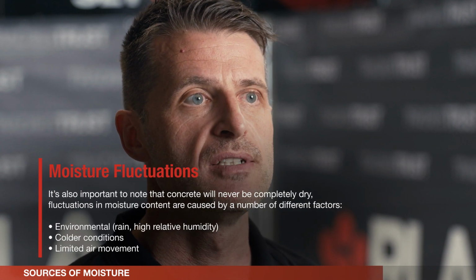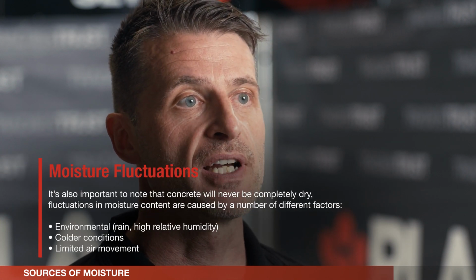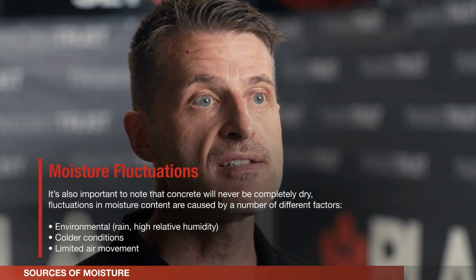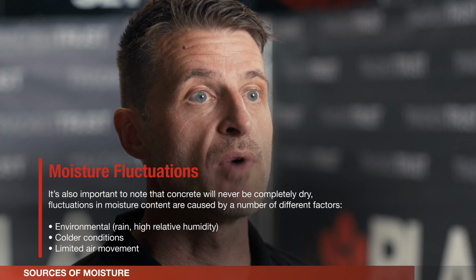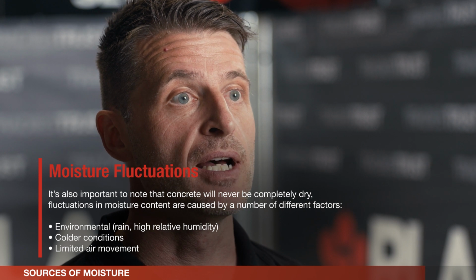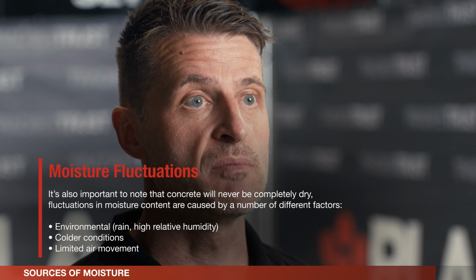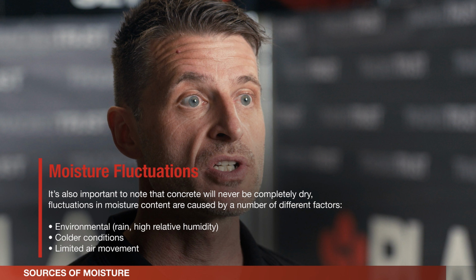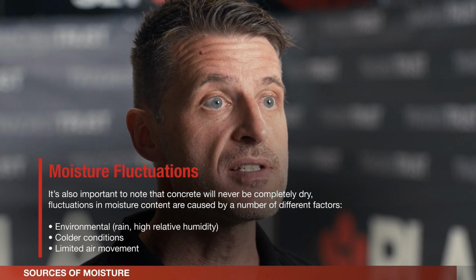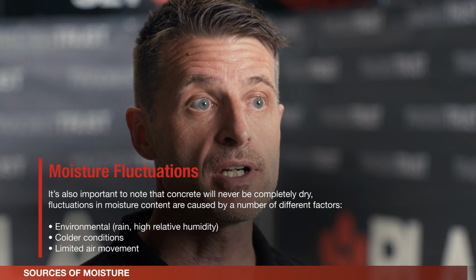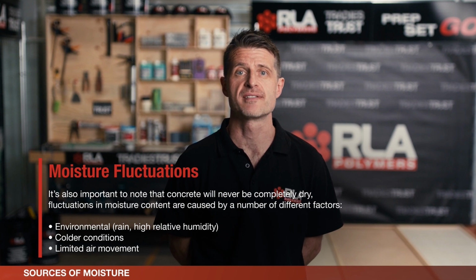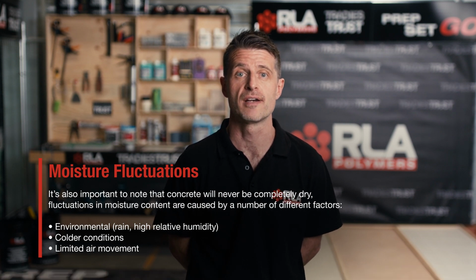Now it's also important to note that concrete will never be completely dry, and the moisture content is prone to fluctuation based on a number of different factors. Things like environmental, through rain, but also high ambient relative humidity, as the slab draws in moisture and it raises the internal moisture content. In colder conditions, moisture is retained in the slab for a lot longer, and limited airflow means the slab will just stay wetter for longer.